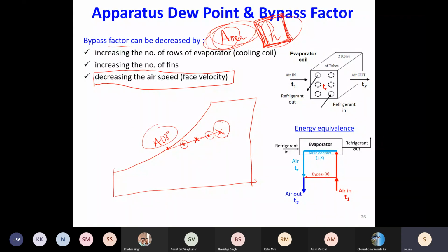And again, this is what your air conditioning system does when you move to your dry mode. It will move to a lower temperature, and it will also move to a lower velocity. You will not be able to control the fan speed with your remote then. If you move to your dry mode, you will see that the option of setting the fan speed is taken away from you. Because if you set it at a higher velocity, you will end up over here. But you eventually want the air coming out of the heat exchanger as dry as possible. So the manufacturer will move to a lower fan speed actually.